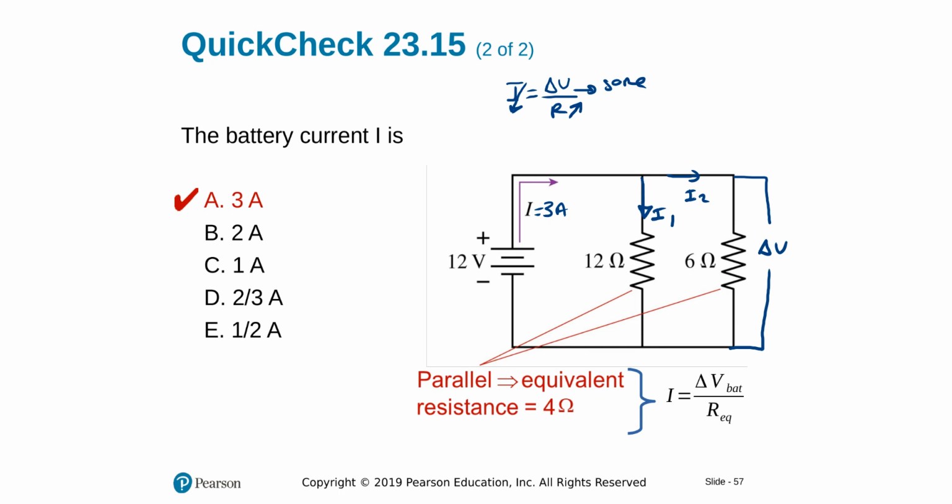In fact, twice the resistance, I'm going to call this R1, will get half the current, R2. So if I have 3 ampere, it will be divided into 3 parts. This guy will take 2 of that, so 2 amperes, and this guy will take 1 ampere. I in is equal to I out at this junction. That should be confirmed by my solution, and it is 2 plus 1, 3 ampere, 3 ampere. Or I can just go ahead and say this. This is epsilon here, or delta V total, right?